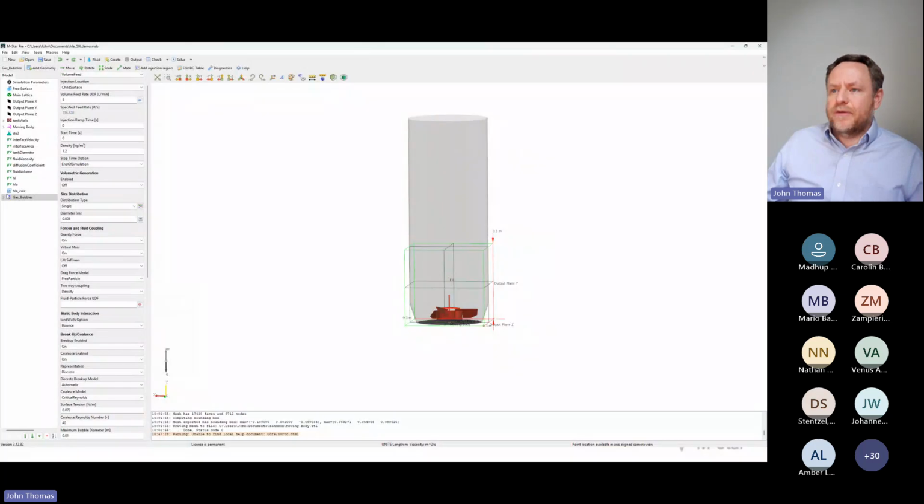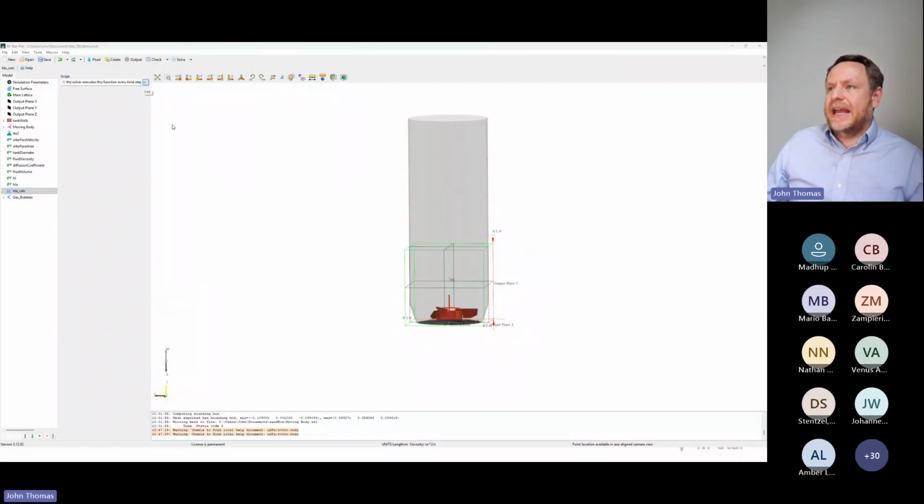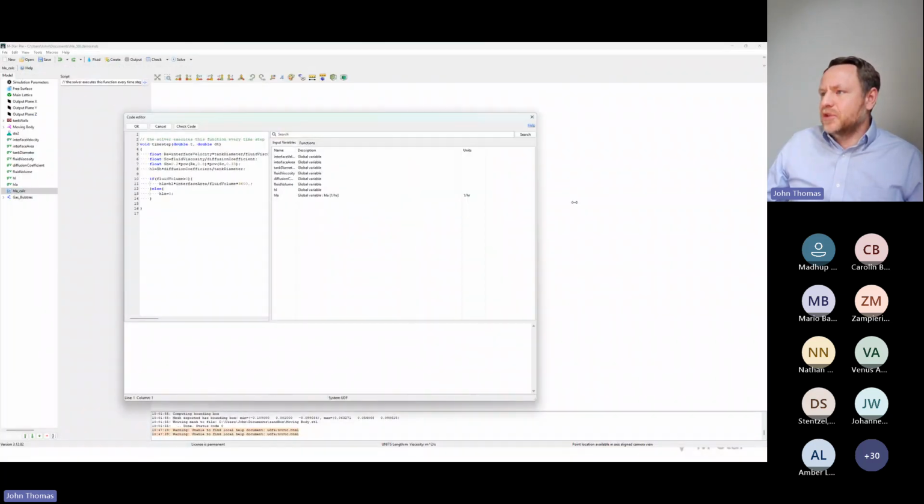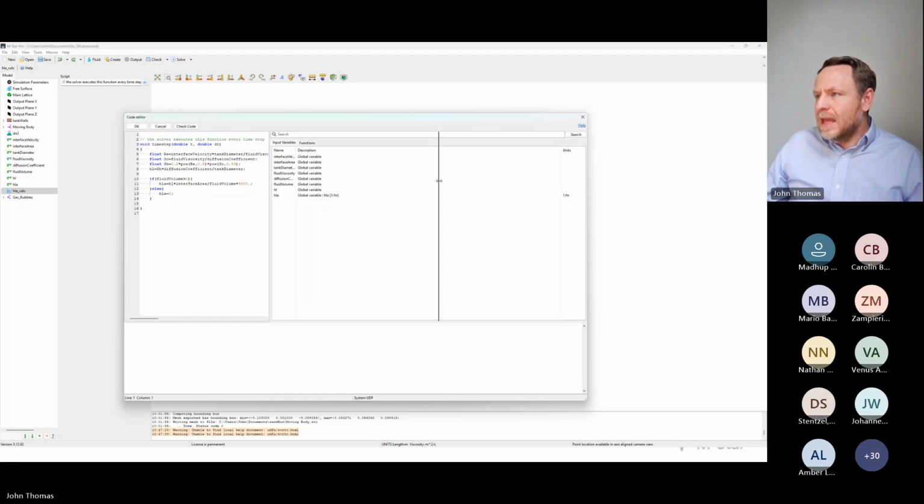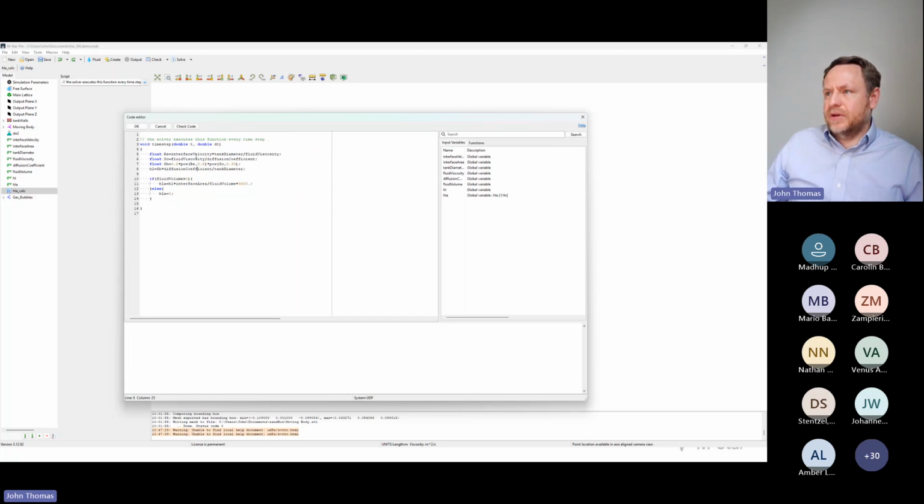And now here's how I'm doing my free surface transport. I'm doing an HLA calculation, just doing this on the fly. I'm calculating my interface Reynolds number using my interface velocity. I'm calculating my Schmidt number. I'm calculating Sherwood, dimensionalizing it, and then calculating HLA: HL times interface area divided by fluid volume, converted into reciprocal hours, as it were.